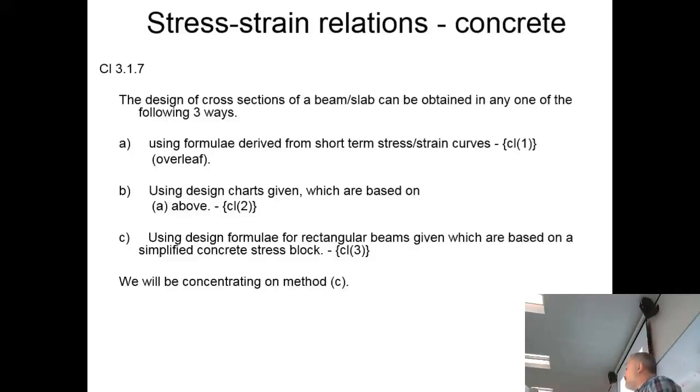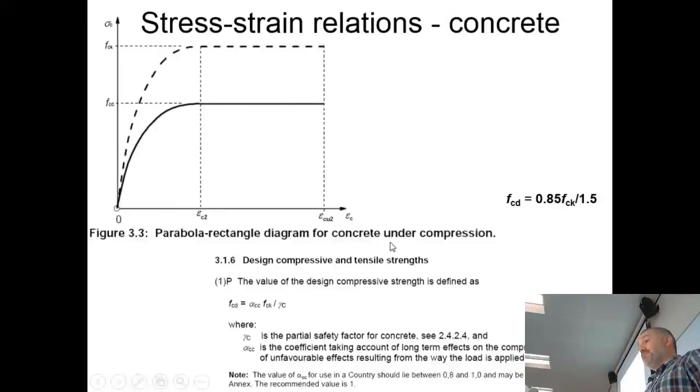What you'll find when you come to industry, you'll be using these flow charts in the stress block, but in order to speed up the process, and you'll see within the Concrete Centre, you've got all of these charts with curves on, and sometimes that speeds up how quickly you can do the design of single reinforced or double reinforced. In terms of what we'll be going through, the stress block option.